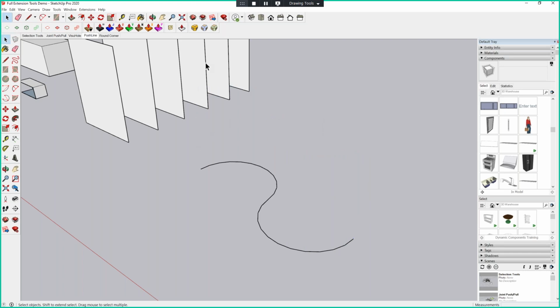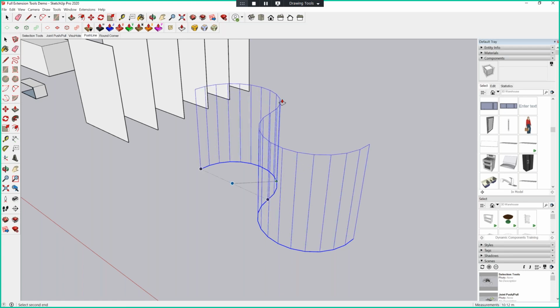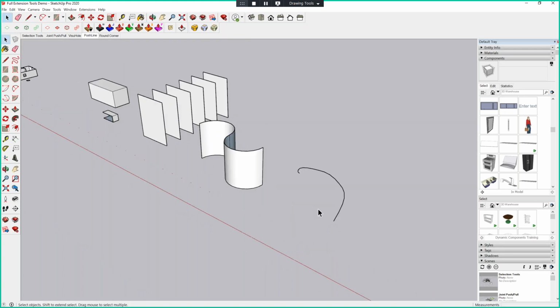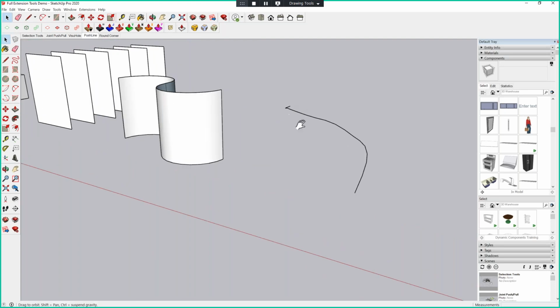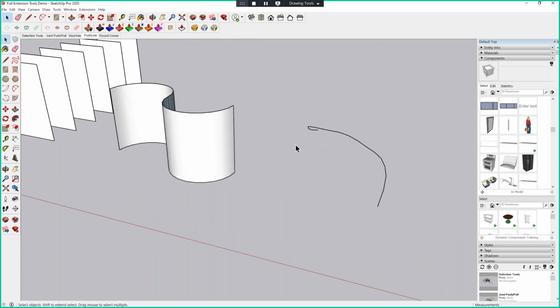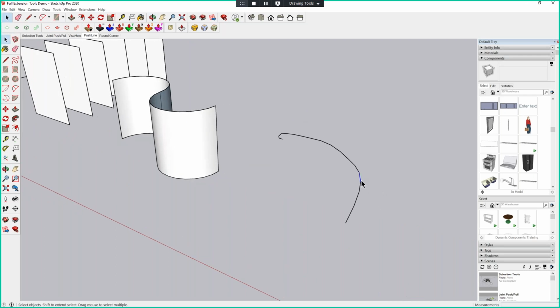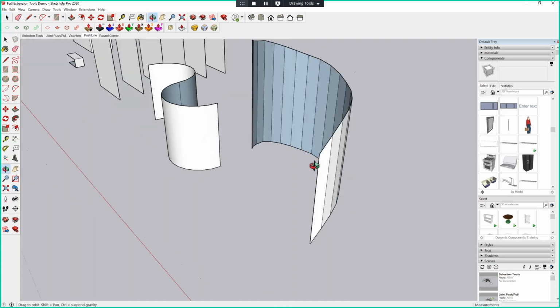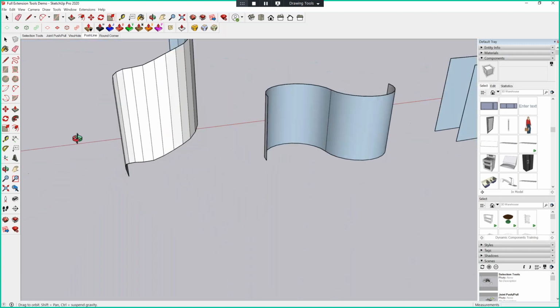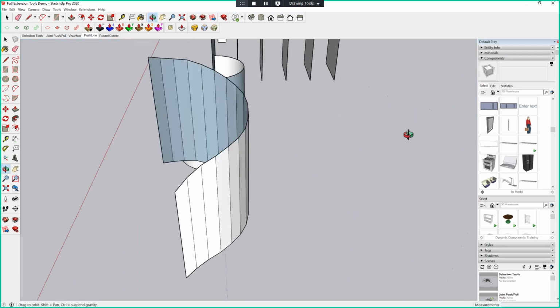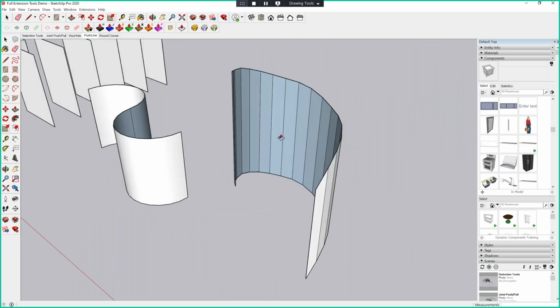That's where push line comes into play, where you can create many different flexible surfaces just by drawing your lines. A very simple tool, but definitely a very handy function. The last one I'll show you is a spiral line at different elevations going upwards. The push line tool also works in this scenario, even if your line is at different elevations. Bringing up push line, you can see the surface is created like a spiral upwards. You really have the freedom to explore all the different surfaces that you can create with your push line tool.